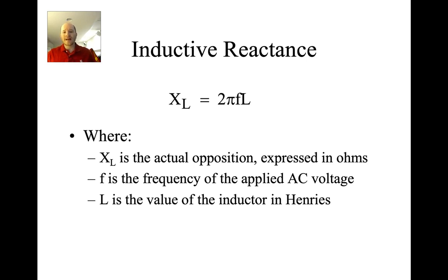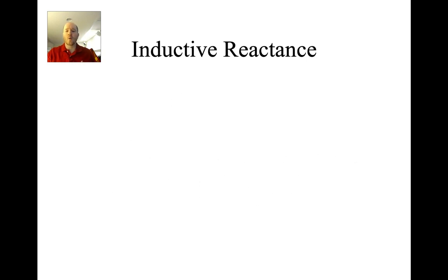Now let's talk real quick about why an inductor reacts this way to AC. When the AC is coming up, the magnetic field builds, and it's fighting that current the way that it builds. Then when it starts to go into the downturn from 90 to 180, that magnetic field collapses, again inducing a voltage to go with it.